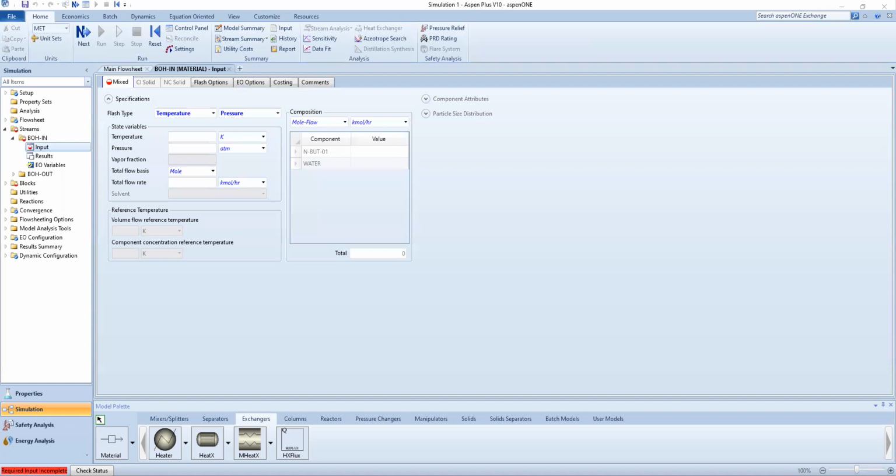Okay, and here I'm just following the figure in the tutorial, and I have temperature, pressure, 117.7, 2 bars, and 1,000 kilograms per hour. So here in Celsius, I have 117.7. Pressure here is 2 bars. My flow rate is a mass flow rate. Again, be careful with this.